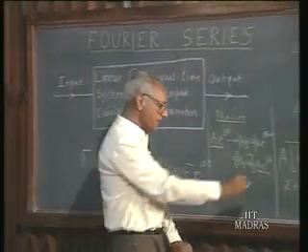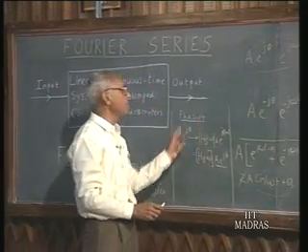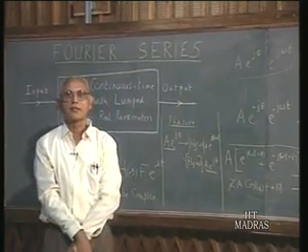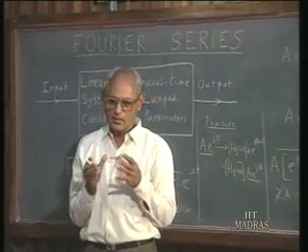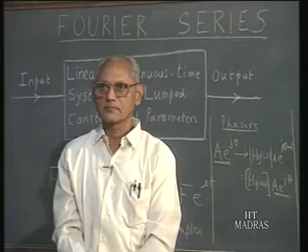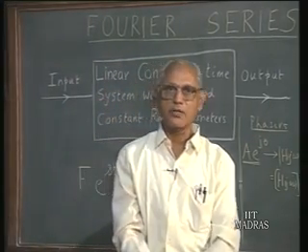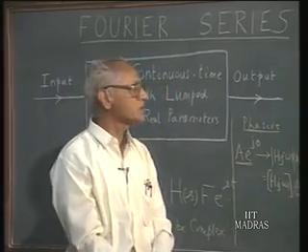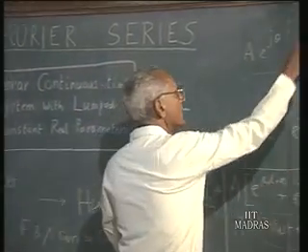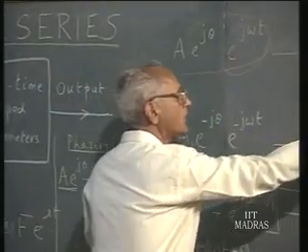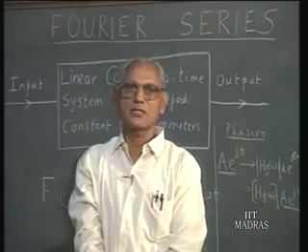So instead of this signal, we are using this, and our phasor is related to this simply by dropping out e to the power of j omega t, because in AC circuit analysis what we normally have is all sources of the same frequency, single frequency excitations, wherever number of generators there may be, but all of them will have the same frequency, and therefore this omega is constant right through. So e to the power of j omega t is a term which is invariably present both in the output and the input. Therefore, it's a term which we can drop, it is understood.